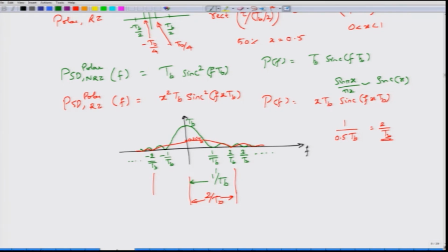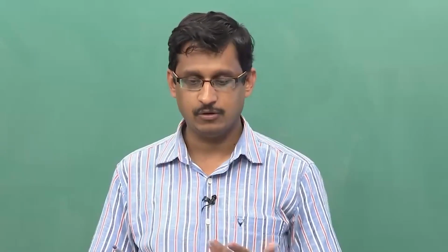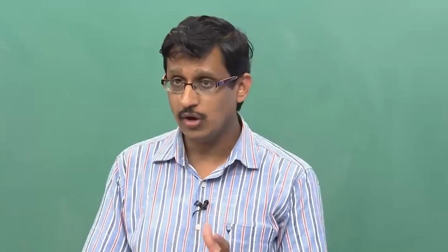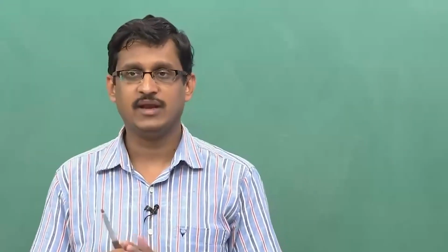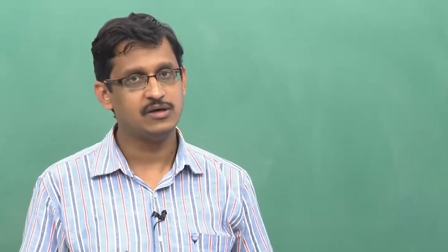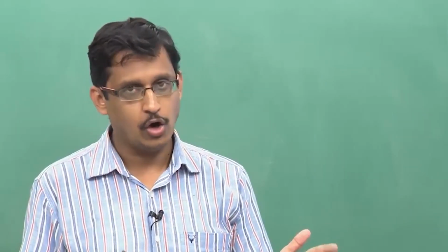So, with RZ you see that there is a larger bandwidth requirement compared to the NRZ format. So why are we even wondering whether to use NRZ or RZ? If our goal is to reduce the bandwidth, then NRZ is preferred over RZ. However, with NRZ it turns out that the pulse is on all the time.